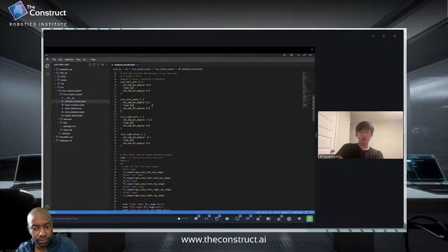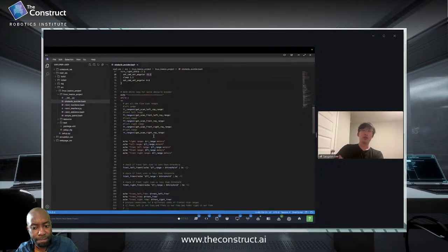It'll go for, so this is the duration times the speed. It gives us the radians, but I'm going to have to change it to degrees. So I pretty much use the calculators, or I Google to see how many degrees it's going to turn. And right is negative because if you turn clockwise, it's negative on the circle thing that we learned in high school. So that's why it's negative for right. It might be confusing for some people. Clockwise would be negative, counterclockwise positive.